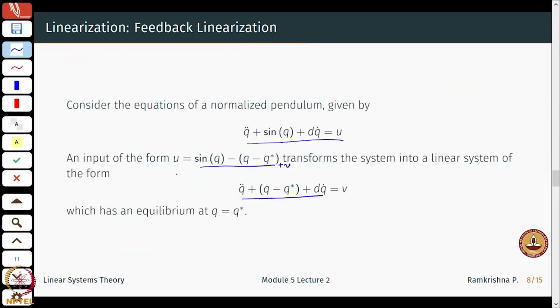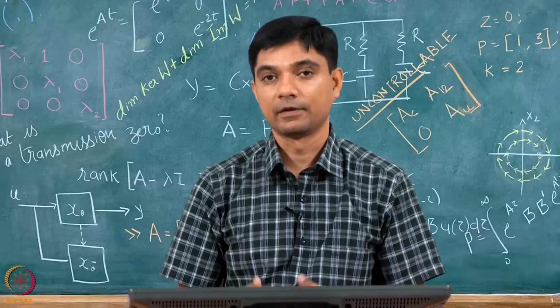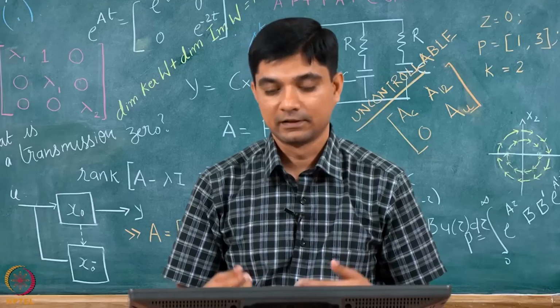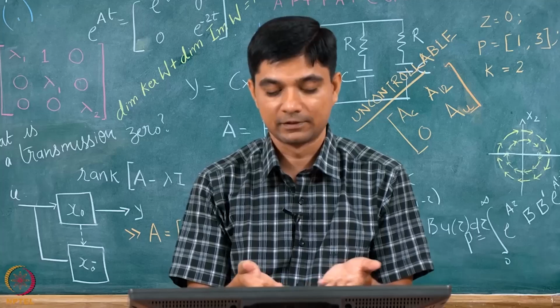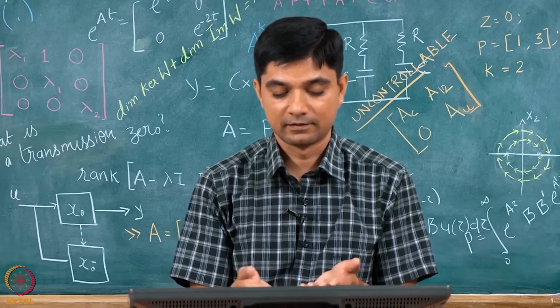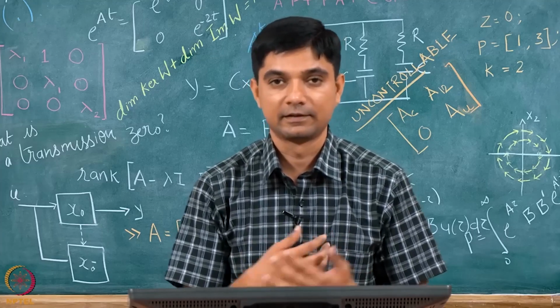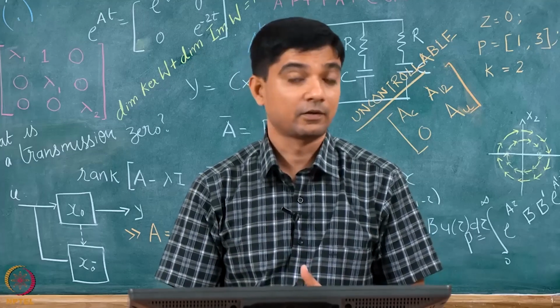Similarly, what I did essentially here is that I used a state feedback, a nonlinear function of the state, to kill the nonlinearity. The nonlinearity here comes from the sinusoidal term. So, this is also called feedback linearization. Now, can I do this all the time? If this was so simple that I could just kill the nonlinearities, mathematically here I am just adding a sine term to the input and the nonlinearity disappears. Now, can I do it all the time?